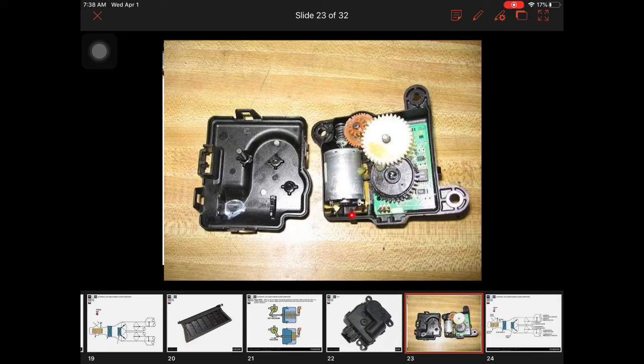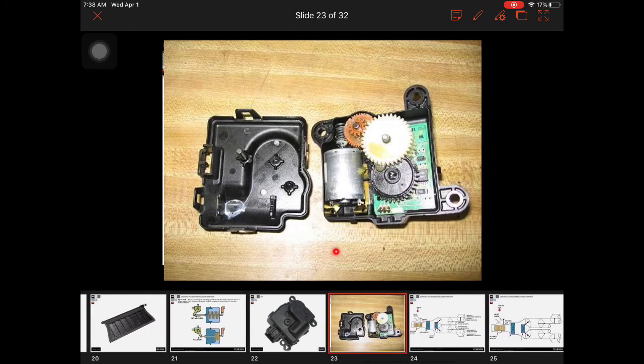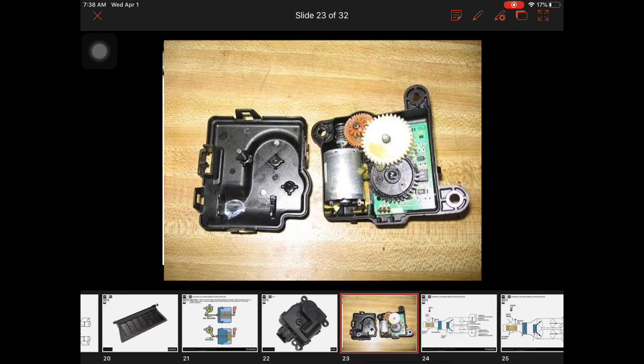So this is actually a logic controlled motor. What that means is that we are actually forcing this thing to spin 1 revolution at a time, and it has a feedback circuit that we can count the revolutions. If you were to watch this on a scan tool, it'd probably be between 0 and 255 counts. So basically you can have up to 255 different door positions depending on where this motor is actually at, okay? So every revolution of this motor is a very small movement of the door, and that's how we're able to control it logically, okay?